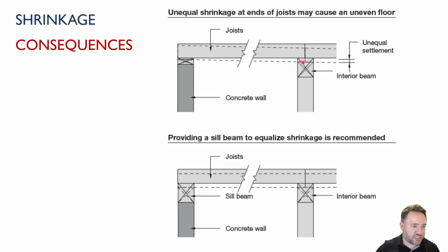Here we're showing just the vertical shrinkage. But you know as well that it's going to also shrink in the horizontal direction, these pieces. So if those two are different heights, we know that the percentage shrinkage of the two is going to be the same. They might shrink 4% or something in that direction, but it's a percentage of the total dimension of that piece of wood. So if I have a small piece that shrinks 4%, that 4% is going to be smaller than if I have a big piece that also shrinks by 4% of its dimension.